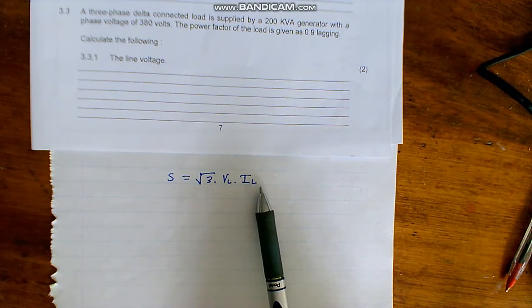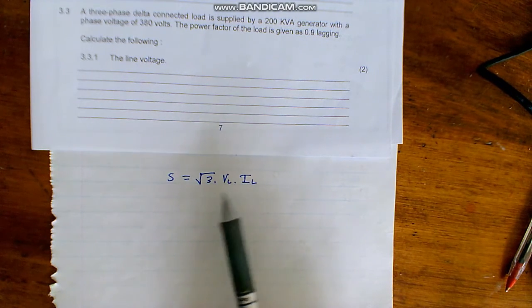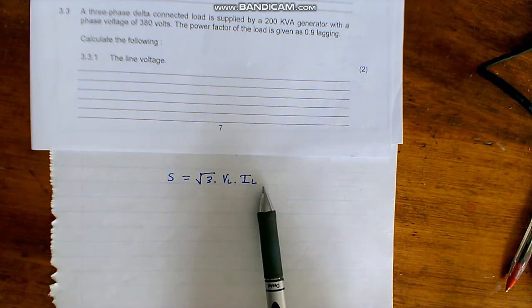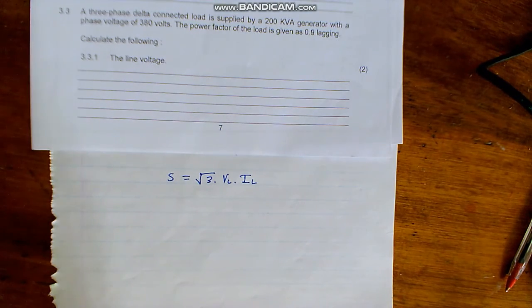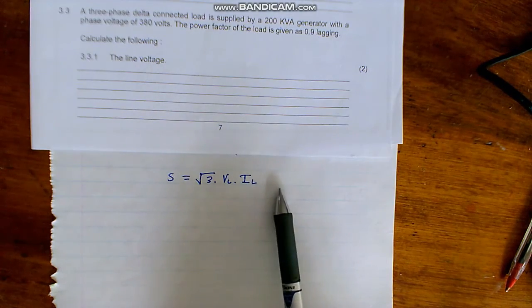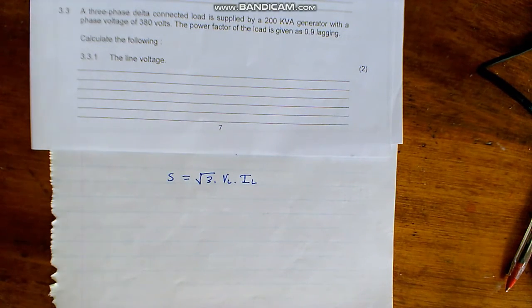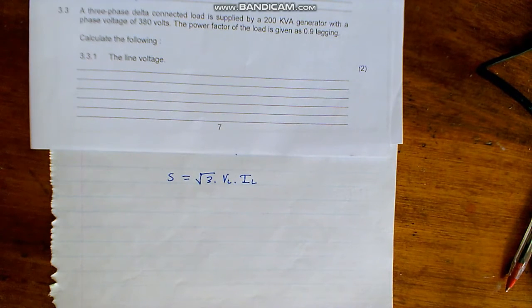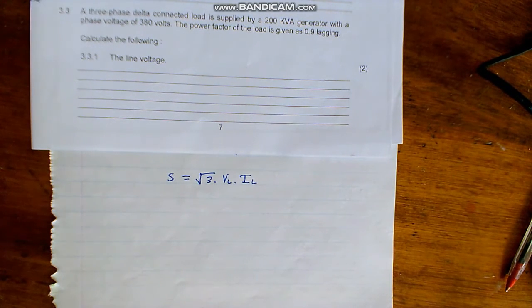Some of these questions you find they calculate the IL and they do not take the power factor into consideration, especially when it's in a delta connection. But if you had to include the power factor, they will still give you the full marks, as I've noted in some other questions. So if they put the power factor there, I would say use it. So our formula there we'll use is root 3 VL IL cos theta.